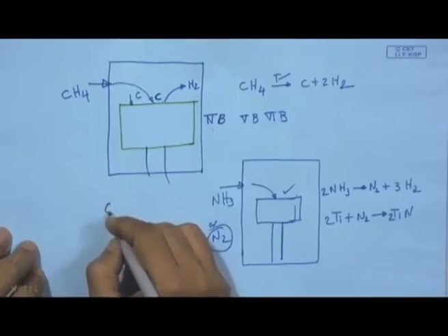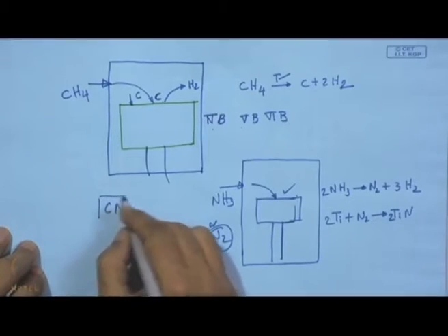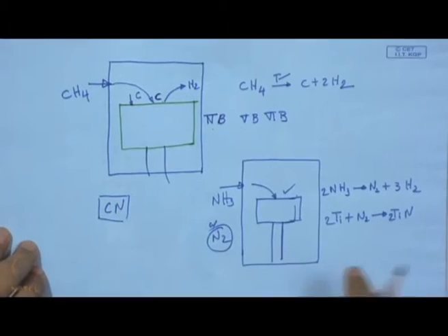Carbides are known for their hardness, whereas nitrides are more important in terms of anti-welding property or chemical stability. If we like to have some balance in between, we can also have a carbonitride coating. In that case it is called carbonitriding.